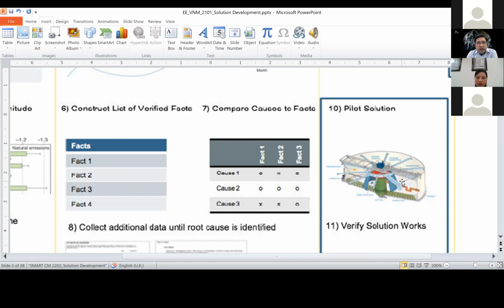So when we had issues related to steam trap leakages, for example, we ensured that they make an SOP for procuring steam traps for next time. How would they measure the flow? How would they calculate the size of the steam trap? They had to include this in their procurement policy, that next time when they are procuring a steam trap, it is of a certain type, and it has a certain life.